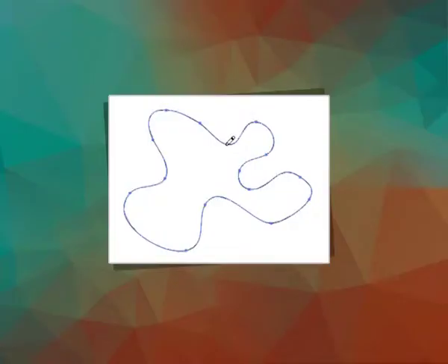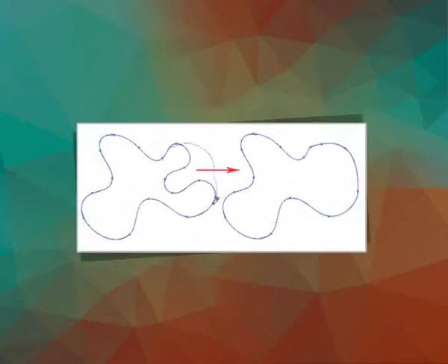Reshaping path. To reshape the path, make sure the path is selected and use the pencil tool to redraw the parts you would like to reshape. Note that the start and end path must be close to the original path for this to work.